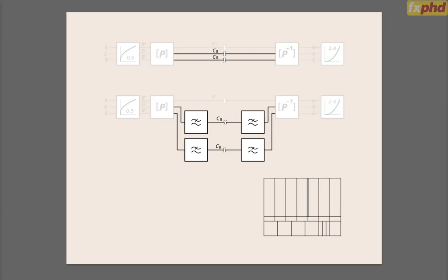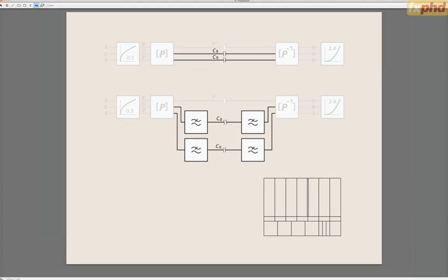So now it's time to introduce the 2 other components, and they're the color difference components. They're called CB and CR. So I'm going to add those or insert those in addition to the Y prime. Now, because we're not using the color scientist's block diagram anymore, we are not making luminance anymore. Well, relative luminance, which would have been symbolized Y. We're making a quantity related to luminance, and it's also related to CIE lightness, related to L star, but it's not either of those things exactly.